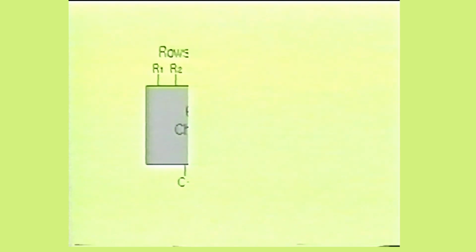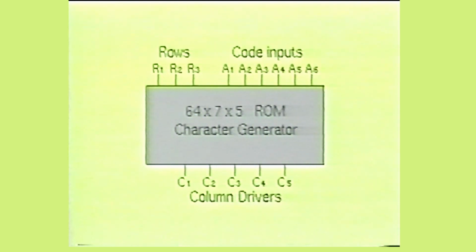It was mentioned earlier that a character generator was required to operate the dot matrix display. The character generator selects the specific diodes to be turned on by a method referred to as scanning. The character generator is generally a ROM device, which is programmed to output 64 characters from a 6-bit address input. ROM stands for read-only memory.